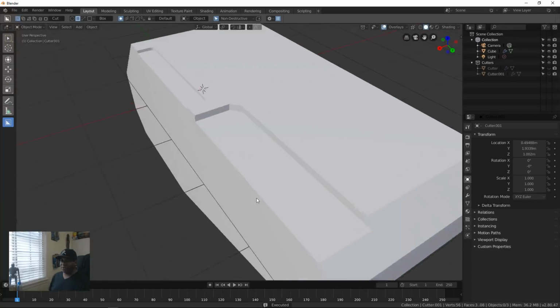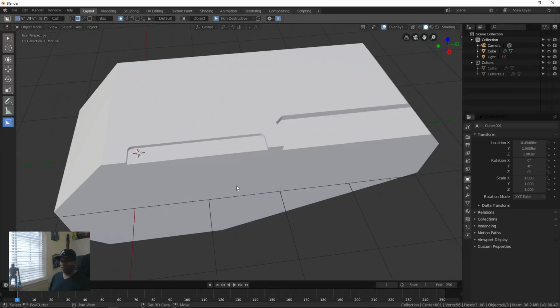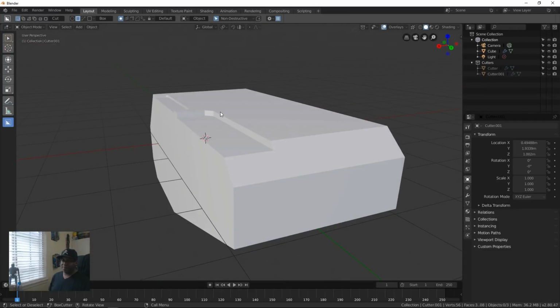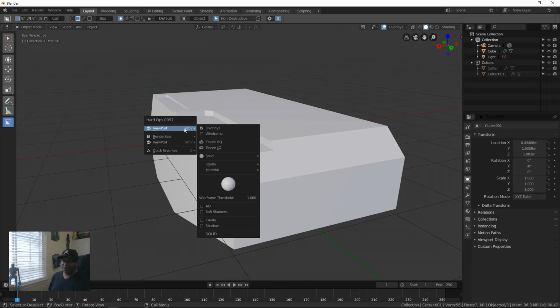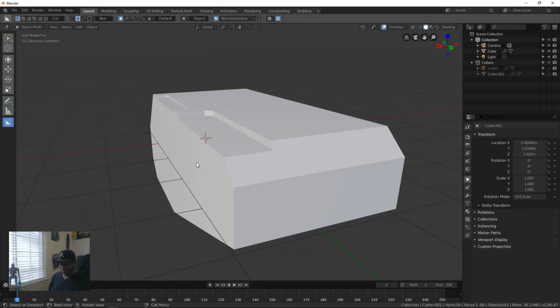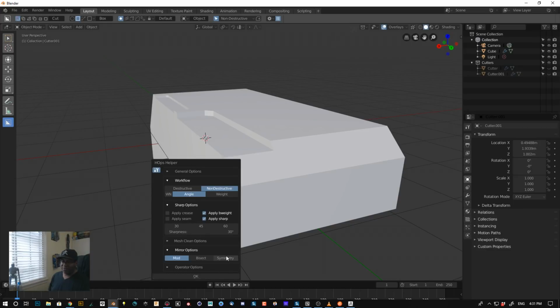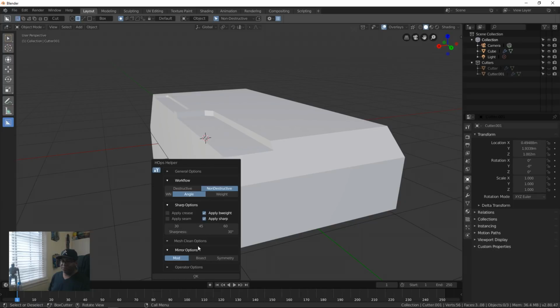And so each time it's sort of like a rinse and repeat, but when I make a selective cut, each time I'm designing into the mesh, each of these modifiers is accessible through a modifier helper, right? So I can hit, I believe it's Control tilde, and that will be the HOPS helper. And then basically I can take that and see what my modifiers are, or start applying some of them and collapsing the list, and so forth and so on.